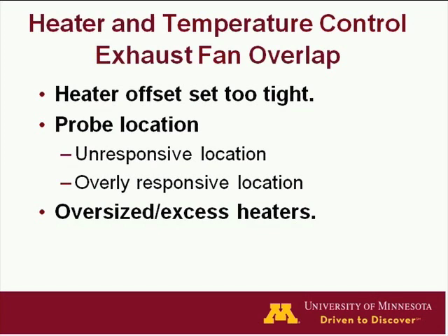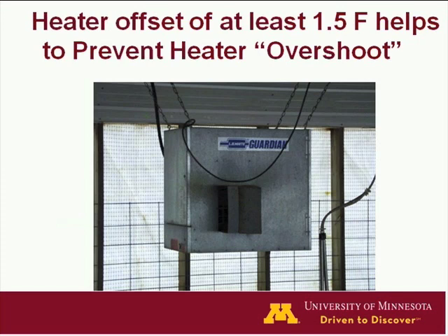Also, the probe location for the controller, you want that in a location that's not too close to a heater or to an inlet. You want that to represent the temperature. So that's pretty important. Most of the time there'll be a couple sensors in these larger rooms. And then the last point there, you've got to be careful about oversized or excess heaters, and that's a pretty common situation.